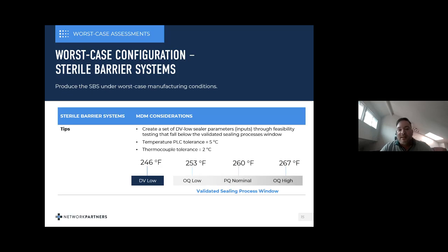So, from that standpoint, when you go into changing your packaging, if I understood the question correctly, you're going to have to go back and probably requalify your sterilizer with a new package. And that should be done anyways to prove out the safety and efficacy, through external process challenge devices, internal process challenge devices. You have to look at your overall package product density, make sure it doesn't exceed what the chamber's already validated for. So it's not a simple answer, but there's a lot of attributes you have to really evaluate and look at to make sure.